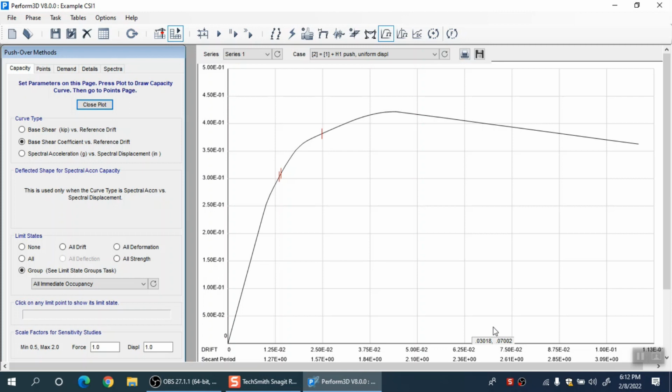It is also called base shear, because when you sum all the applied forces, it should be equal to the base reaction, right. So on the y-axis we have the applied force. You can see that up till a certain deformation level and force level, the structure remained linear, but then it deviates from the straight line. Now you can also see some cuts in red color here.